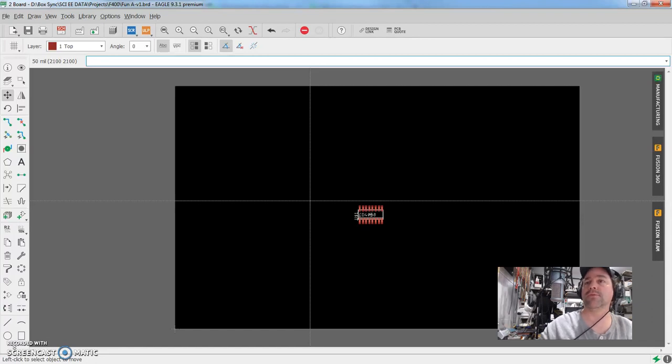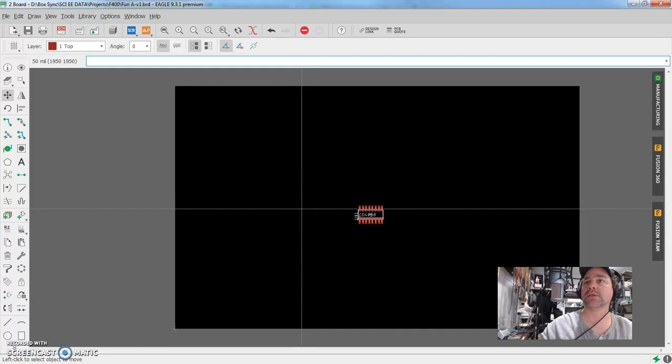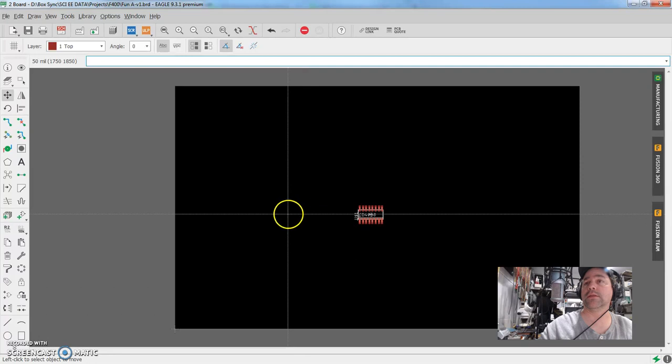So if I want a 16-layer board with all kinds of blind and buried vias and controlled impedance and micro vias, because I've got a big BGA that I want to put on my fancy design, all of that is perfectly fine, except that the cost of that board is going to be enormous compared to a simpler board.